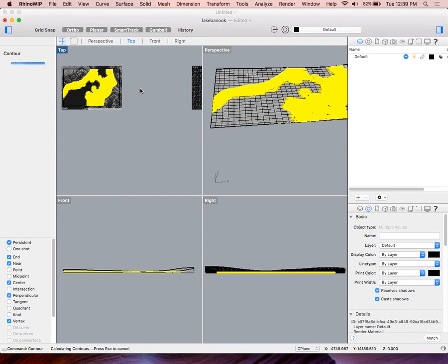Additionally, if any of you are really comfortable in Rhino, I don't have Grasshopper on my computer here, but I have a Grasshopper file that automatically does this: if you build all of these houses in SketchUp or even in Rhino on a flat surface, it'll bring all of these houses or buildings down and rest them perfectly on your new terrain, even if you have a super steep site.